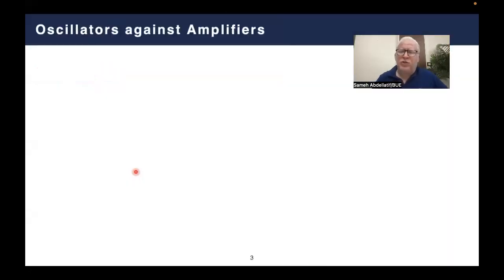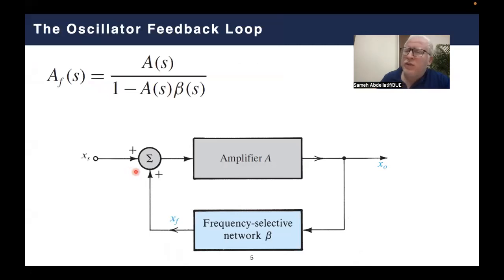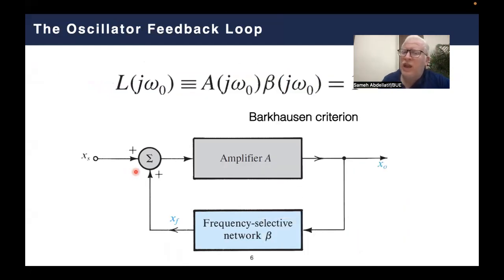in the previous lectures, we have demonstrated the main idea of an oscillator constructed of an amplifier and a frequency selection network, or what's called a beta network, where we reached a conclusion that the oscillating frequency is the frequency at which the condition A beta equals 1, considering that generally speaking, the A network or the amplifier can be S-dependent or in terms of J omega, and of course the beta selection network is also an S-dependent or J omega network.